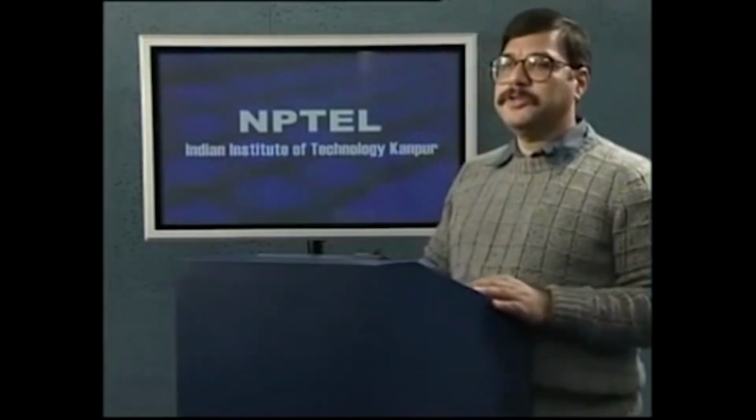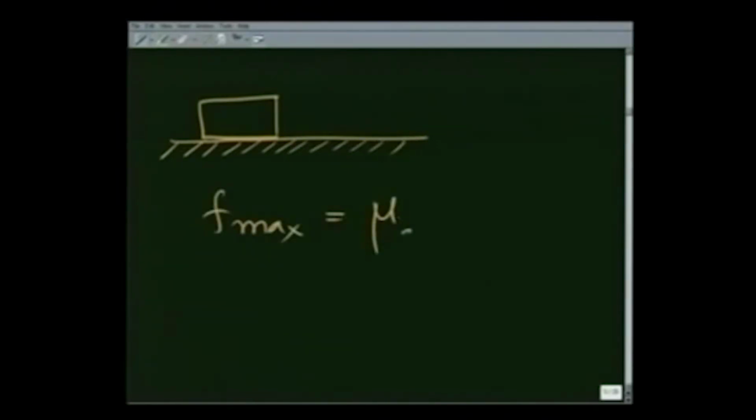So the maximum frictional force on a block on a surface is given by F max, which is mu s times N. If I apply a force here, the frictional force adjusts itself so that the body doesn't move.